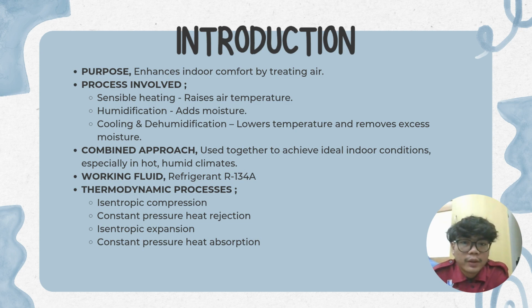First thing first, for the introduction, the purpose of air conditioning is to enhance indoor comfort by treating air. The processes involved are sensible heating, which raises air temperature, humidification, which adds moisture, and last, cooling and dehumidification, which lower temperature and remove excess moisture. For the combined approach, these are used together to achieve ideal indoor conditions, especially in hot and humid climates.